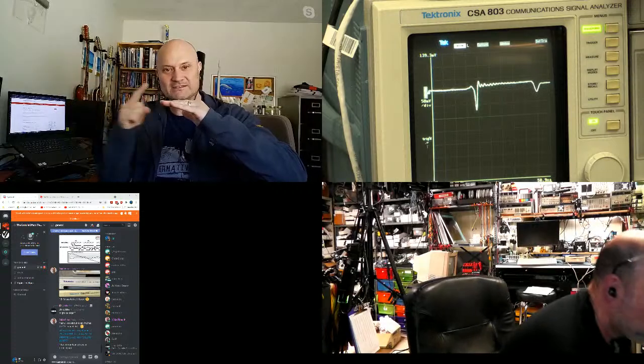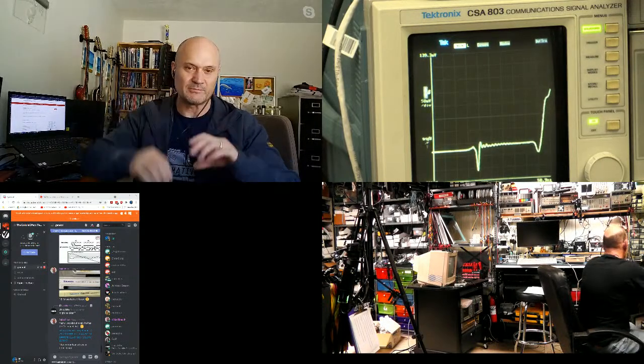After a certain number of time divisions, the waveform would step up again. What we're seeing is the original voltage level of our pulse generator, which is still sending a 1 or plus 5 volts or whatever it was. But sometime later, the reflection comes back up the line and the voltage adds. So we're looking at a stair-step waveform: the first step is the bit we're sending, and the second step is the reflection superimposed over it.